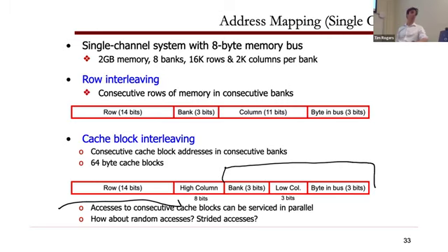Good question. But yeah, you can be more aggressive, right? And again, it just depends on how you define your memory system interface. All of these minute details, this is what's in the JEDEC standard that defines what DDRX is and what GDDRX is and what HBM is.